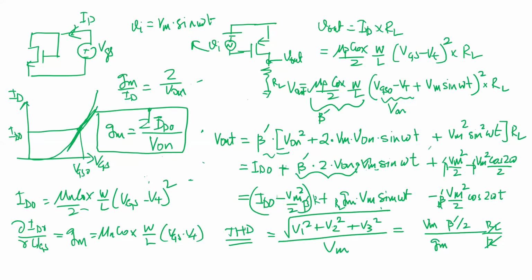So that's what we're going to do. We're going to give a transient wave for what the measurement was done for the op amp, and then do a Fourier analysis of the output and find all the Fourier components. If you have given 1 kilohertz, we'll find the 2 kilohertz, 3 kilohertz, 4 kilohertz components, and then use this equation. We'll take the 2 kilohertz component, square it, 3 kilohertz, square it, 4 kilohertz, square it, add them all up, take the square root, and then divide it by the amplitude of the fundamental, and that will be the percentage. We'll do that when you're doing the overall simulation.